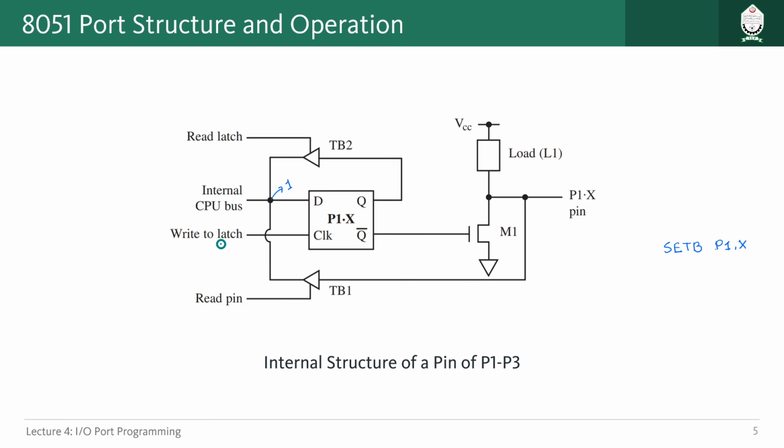We are going to give the proper signal in the clock, so that this logic 1 is latched onto Q. So we are going to get 1 here, and because of that we are going to get 0 here. Q bar will be 0, which basically turns off this MOSFET. So this path is essentially off, right?